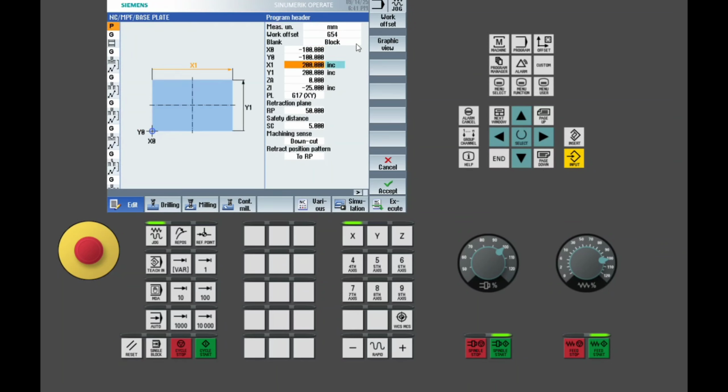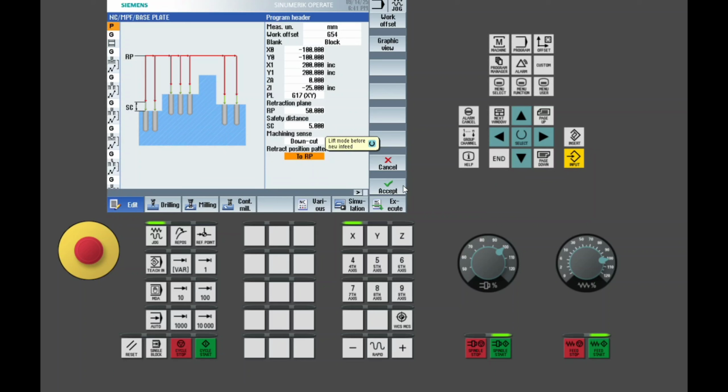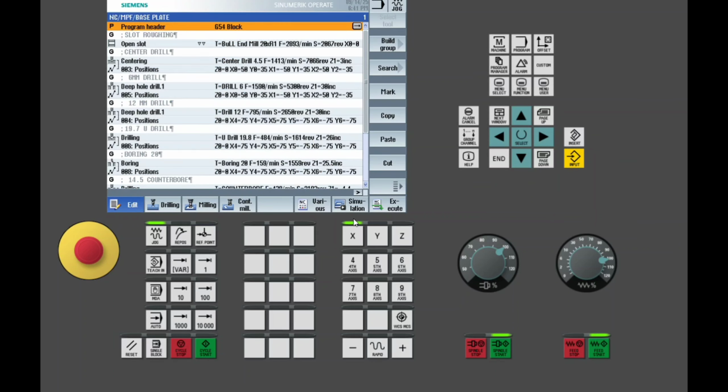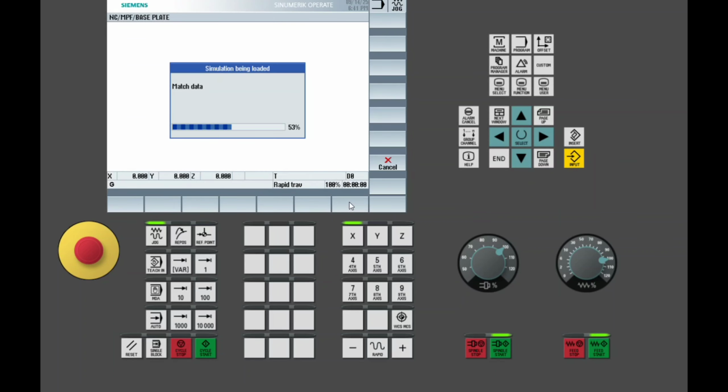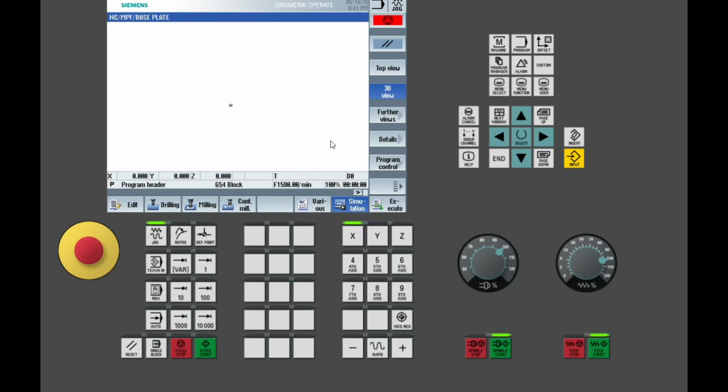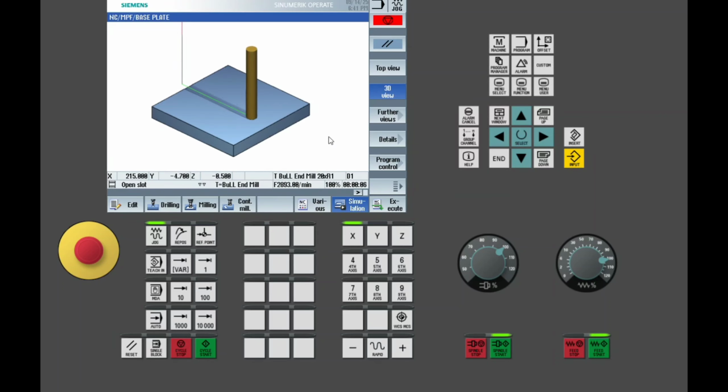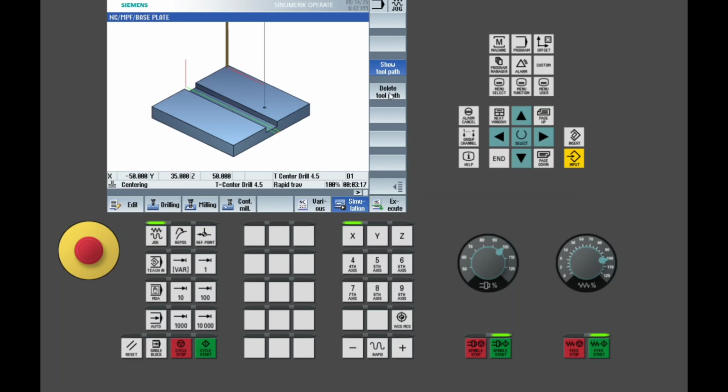First, check the simulation of all the operations. Are all operations working well or not? Select the simulation button to view the tool movement. Start with plunging of the 20 mm bull end mill, achieving the depth of 10.7 mm with 0.3 stock at the wall as well as at the floor. Further, proceed with the center drill and then the 6 mm drill with peck depth.